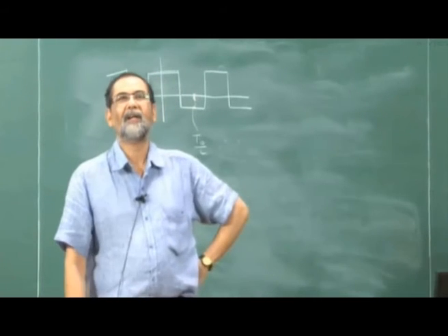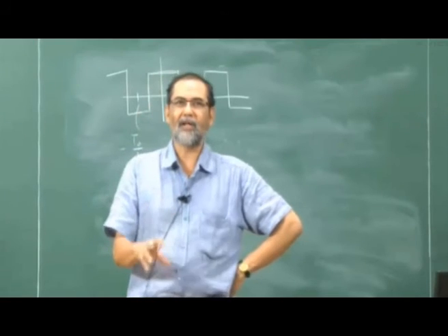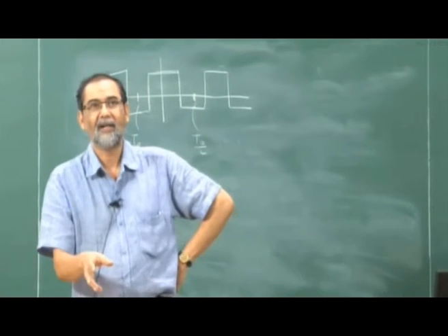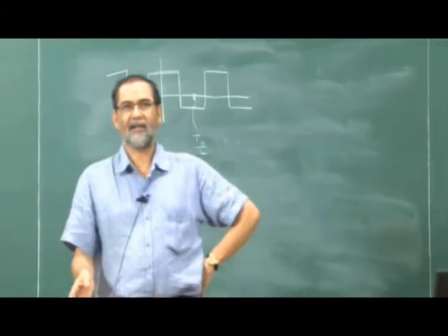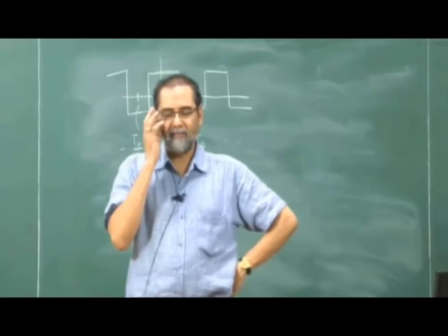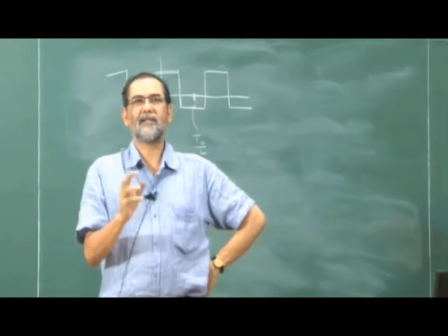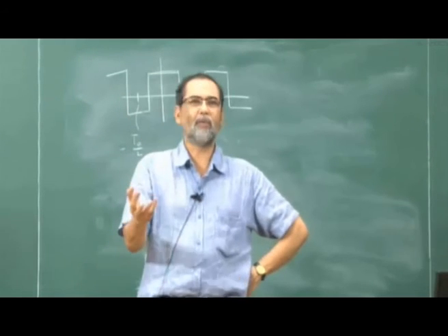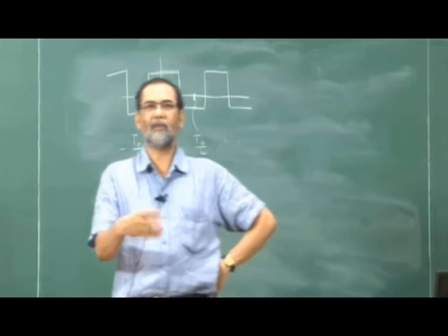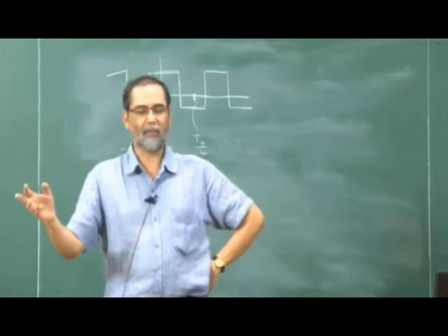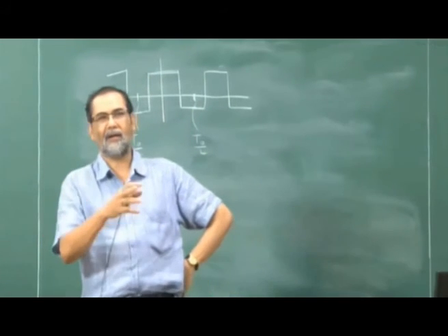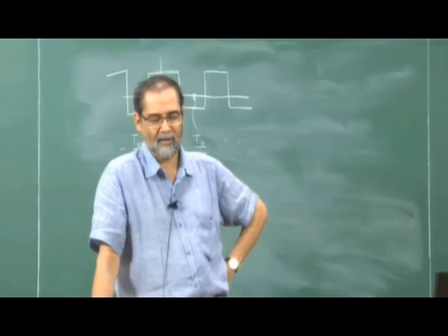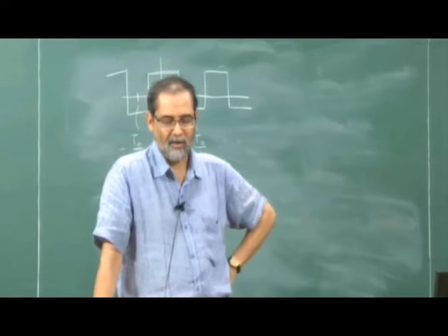The standard trick is, because a periodic impulse train is periodic, you write its Fourier series, right? When you write its Fourier series, it is x_n e raised to j n omega naught t, and you take e raised to j n omega naught t and take its transform in the form of 2 pi delta omega minus n omega naught, right? And so you could write the Fourier transform for the impulse train.